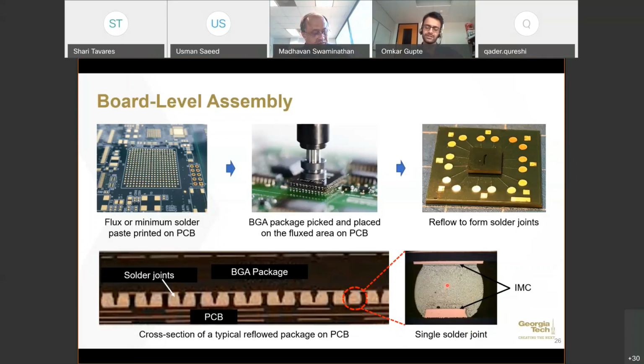No, it would be at the same, because the solder material is the same. If it's SAC 305 solder, for that to melt we would take it to the same temperature, typically about 245 to 250 degrees max temperature. And in that case, the intermetallic on the substrate side will keep on growing at that temperature while this is being formed.